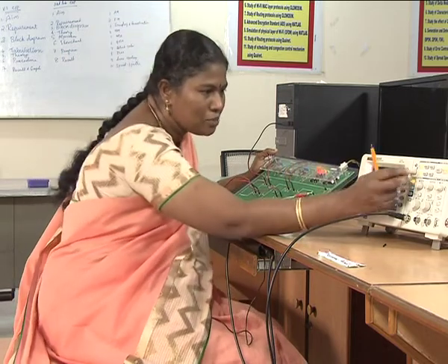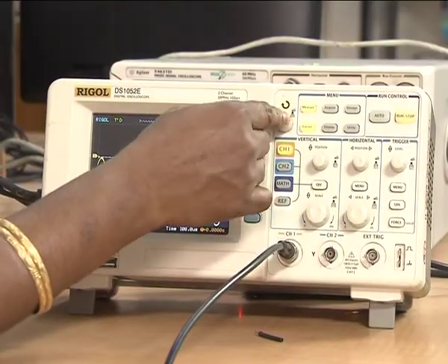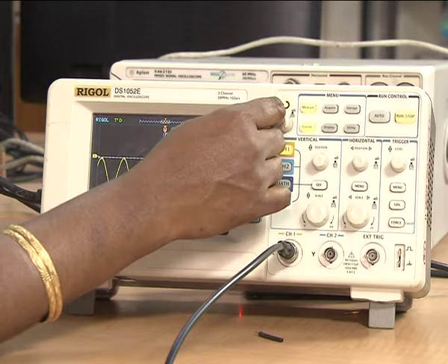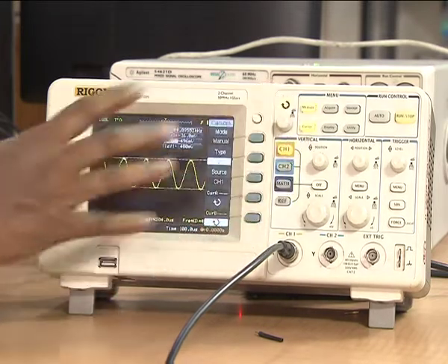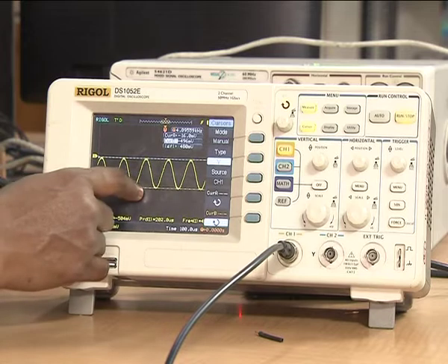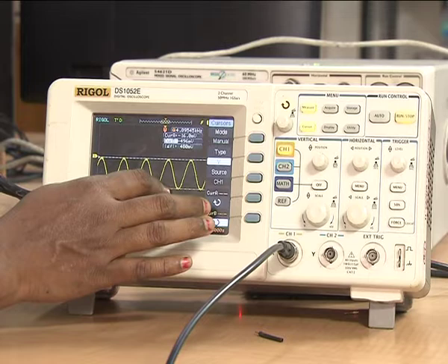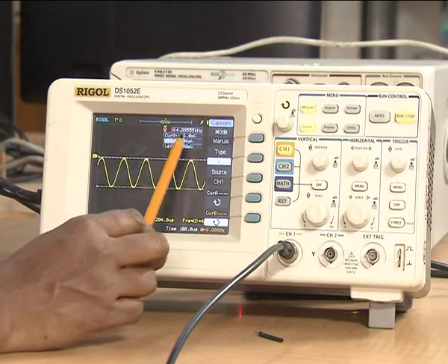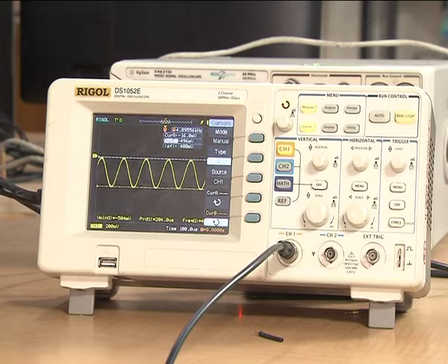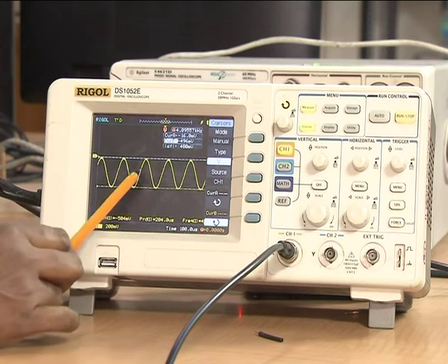Here also you can measure the peak to peak signal by adjusting the cursors. Cursor A is placed over the top of the sine wave and cursor B is placed over the bottom of the waveform. Now, you can measure the peak to peak voltage, that is del Y, which is nearly 400 millivolts, the amplitude that we provided at the input. The frequency of this signal is nearly 4.8955 kilohertz, which is approximately equal to the 5 kilohertz generated by the kit. So, this is approximately 5 kilohertz, and this is the voltage signal that we have set.